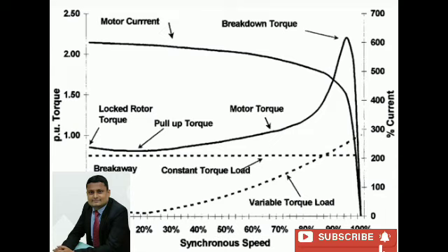Friction and windage loss. You can learn the value, suppose that a 0.75 kilowatt motor is there. So friction and windage loss, in brackets percentage of output, will be 5.5% for 0.75 kilowatt, 2.7% for 7.5 kilowatt, and 1.0% for 150 kilowatt.